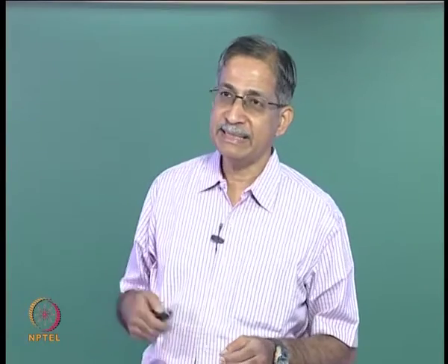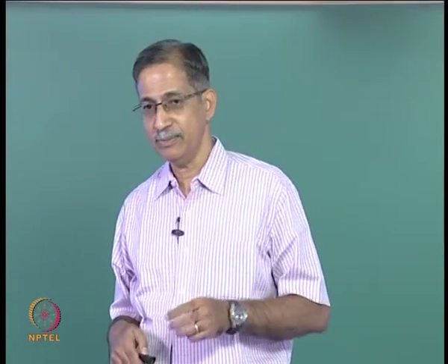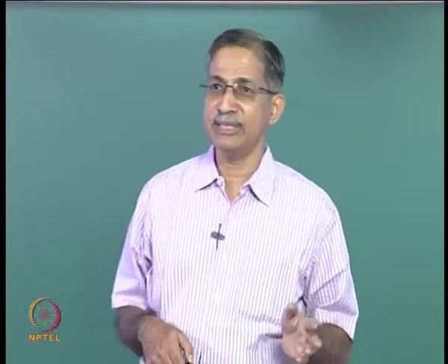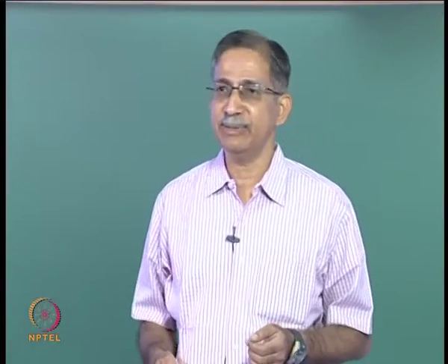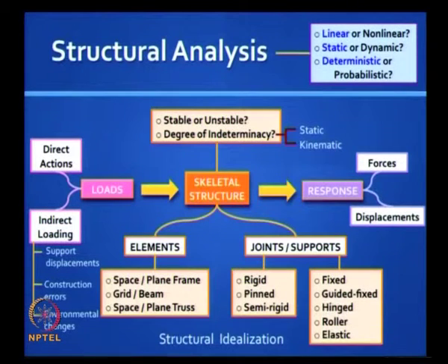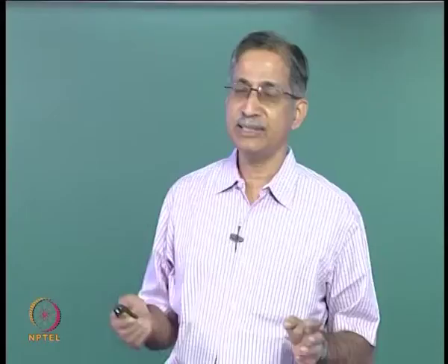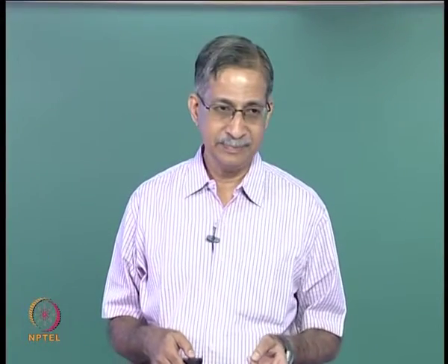So you have to look at the degree of indeterminacy, which is the degree of static indeterminacy versus the degree of kinematic indeterminacy. And of course you have to decide on what level you want to do this analysis. So do you need to do a non-linear analysis, which is a little complicated as you know, or is it enough to do a linear analysis?